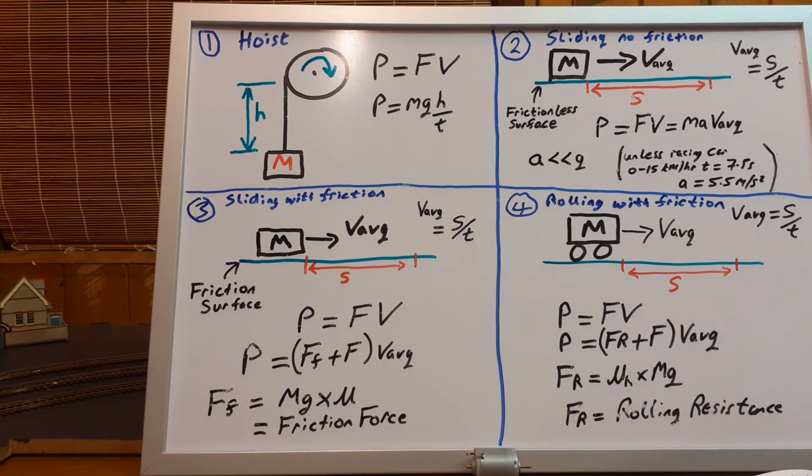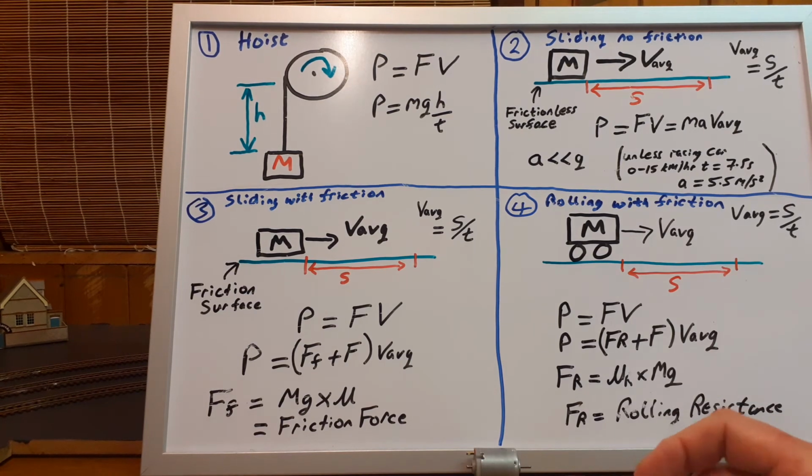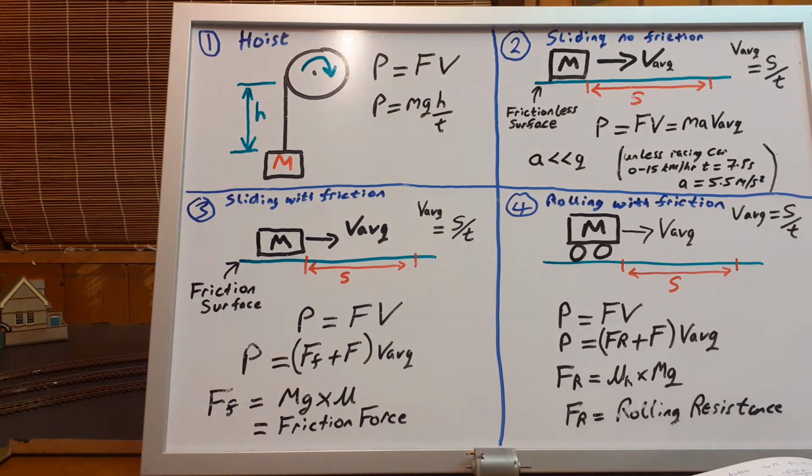So in conclusion, what do you do? You want to get a motor for your project. You need to decide what the mass is that you need to move, or estimate what the mass is, and then decide on what velocity it needs to move at. That can be calculated either in turning velocity, omega, and converted into V, or its linear velocity.